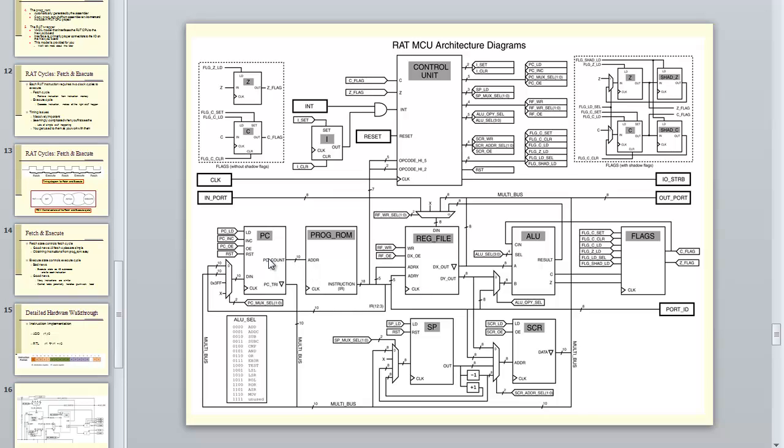Because if you want to do port mapping, you will have to connect all these units by giving them intermediate signal names. So it might be helpful to label all these intermediate signals on a piece of paper so you don't get it confused when you're doing all of your port mapping.